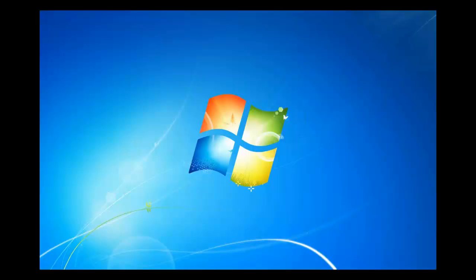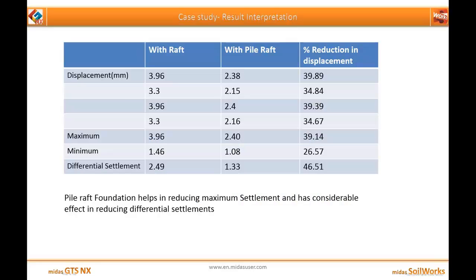So there are few queries like how to decide the mesh sizes. As you can see that we have imported the building model, so we should consider the mesh size such that there is proper nodal connection between the imported beam node and the mesh of your model. So for this I have chosen that criteria, that there should be proper nodal connectivity between the nodes of the imported model and the raft foundation which you have created.